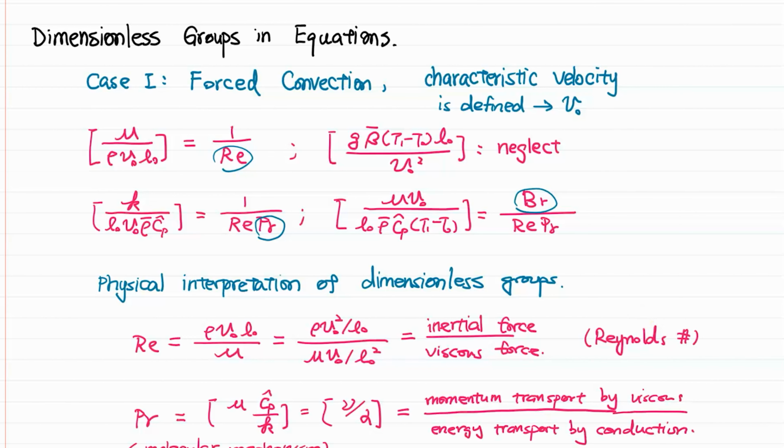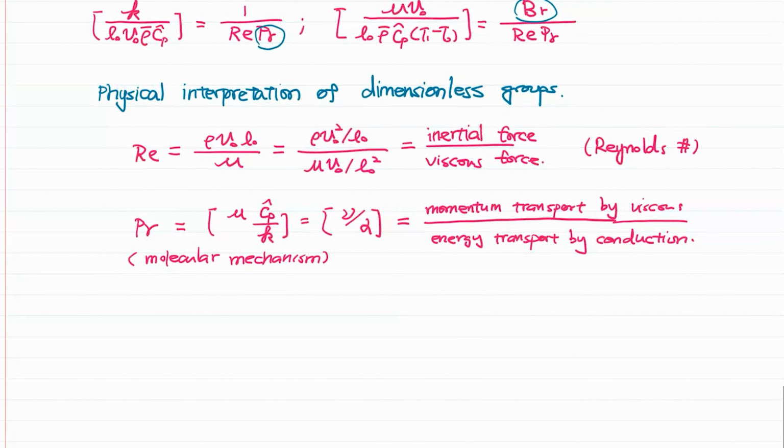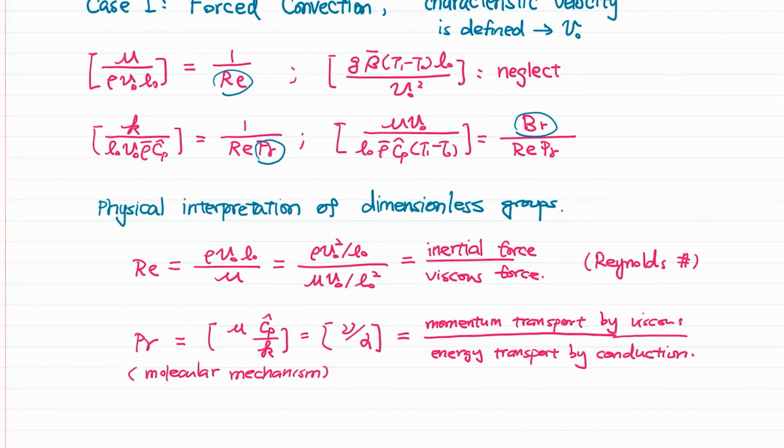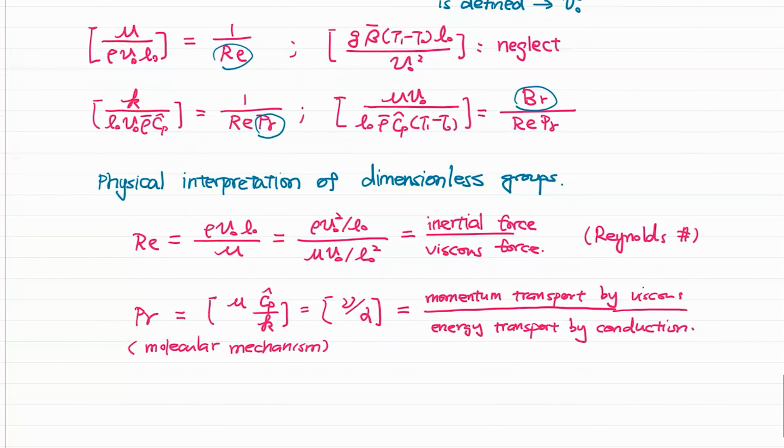Okay, so what that means is that in the equation of energy, if the Reynolds number is very high, or if the Prandtl number is very high, then the first term of your energy equation might also be negligible, depending on its relative contribution to the second term, right? And so we can also take a look at the Brinkman number.